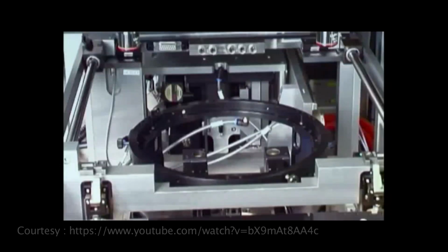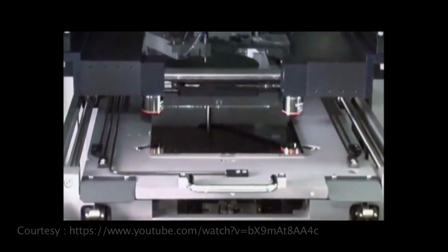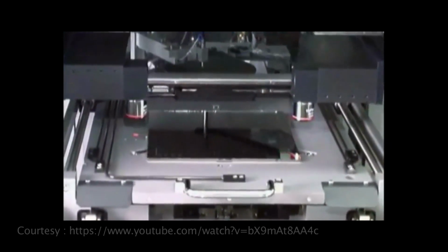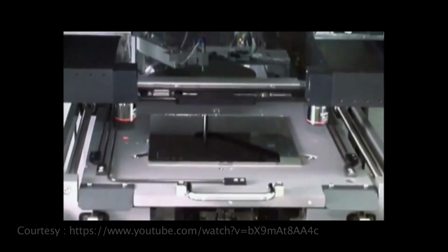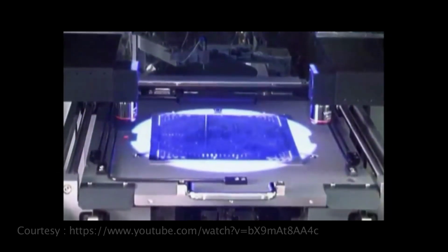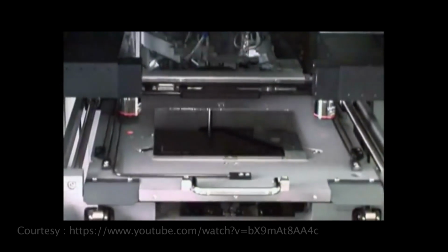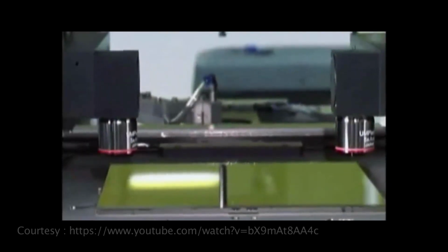Because of the MA200 Compact's newly designed microscope, during exposure, the mirror housing doesn't move forward. The microscopes only move sideways, thus reducing the vibrations of the alignment stage to a minimum, resulting in far greater accuracy. The optics of the MA200 Compact are optimized for thick resist processing.